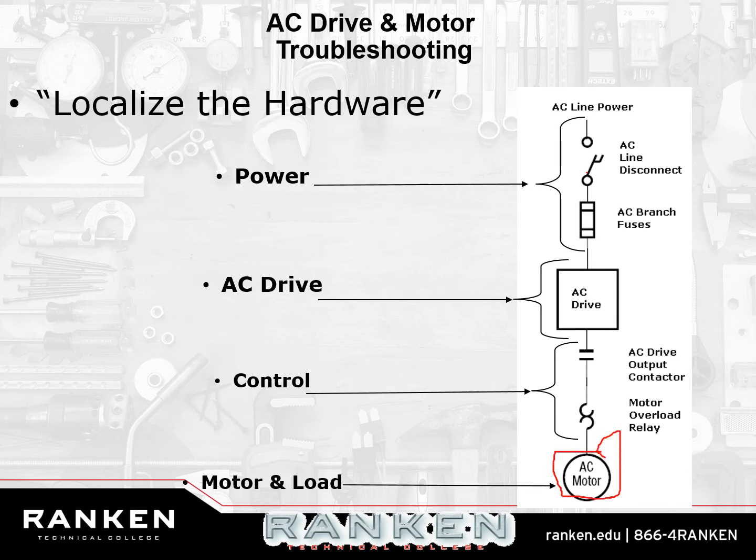If it still won't turn on and all of this is working, I can tell you it's probably the motor or the load itself. Now, in a lot of places, it wouldn't be up to us to go check the motor itself or the load that's on the motor. That would be a mechanic's job. We've identified that it's nothing in our realm of expertise. It's not the motor, it's not the overloads, it's not the contactors, it's not the drive, it's not the disconnect, it's not the fuses.